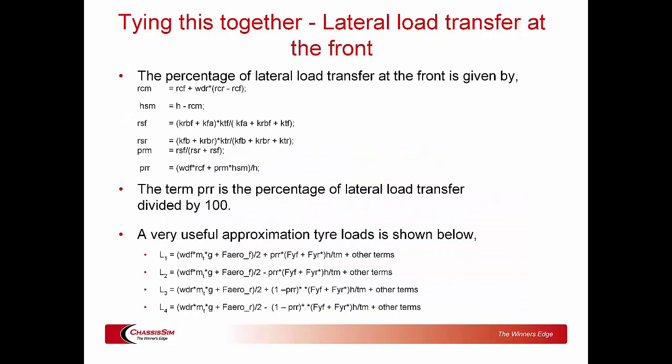Okay, so having said that, how do we tie stability index and grip together? Well, to do that, our first port of call is the lateral load transfer at the front. This is sometimes referred to as the magic number. Now, look, this number doesn't have any paranormal or metaphysical implications to it, but where it is very powerful is it gives us a very good first cut of seeing what a given setup will do. This derivation is something I've discussed in my race car engineering articles. I also discuss it in my book, The Dynamics of the Race Car. But it's a very good rule of thumb.